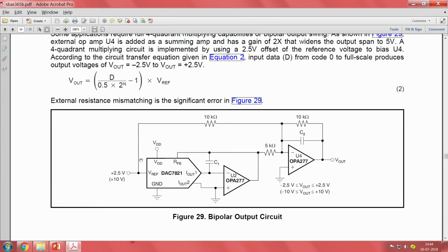This will help you a lot in two things. One is, if you are confused or stuck as to what exact circuit to use for your typical application, most of the time that typical application will be there in the datasheet, and you can borrow from it and then make minor modifications as you want. Another one is, you will be able to see applications which you never even thought of with that IC. So it forms a part of your learning curve also. So you can learn new circuits.